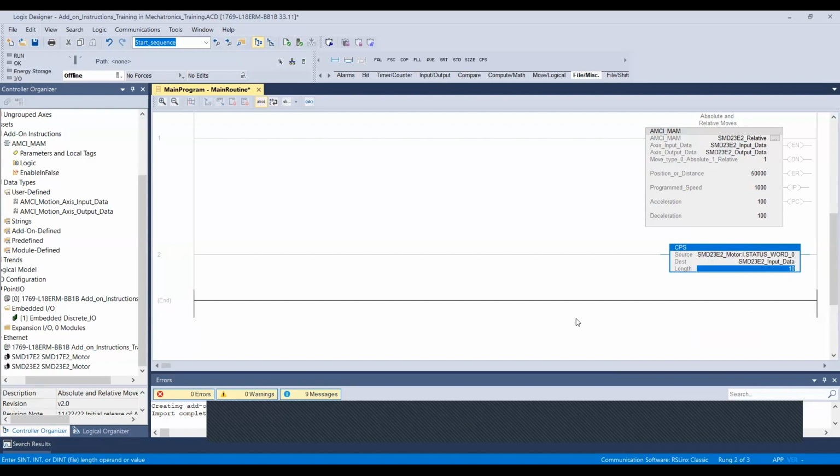You kind of wonder yourself, why not do that within the AOI? Well, it really has to do with the fact that we're showing a very simple example here with only one instruction, but we have multiple instructions. This reduces the number of copy instructions that we have to one, and therefore it kind of prevents situations where maybe something is overwriting somebody else's information, makes it a lot simpler.